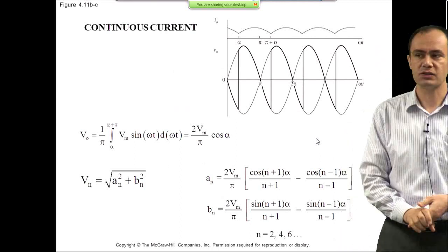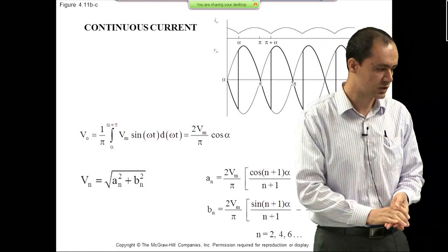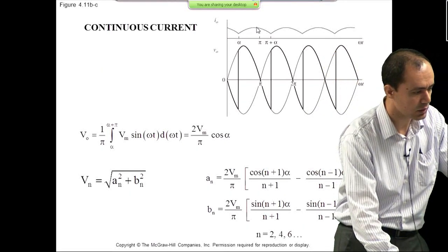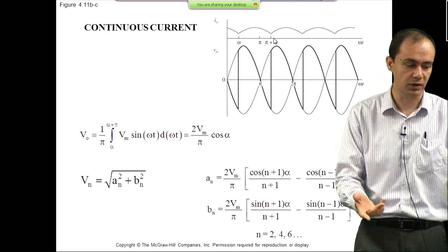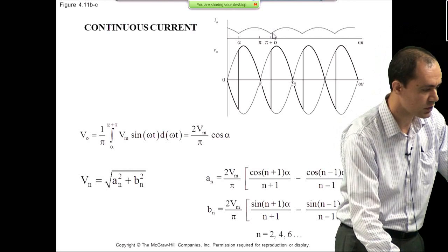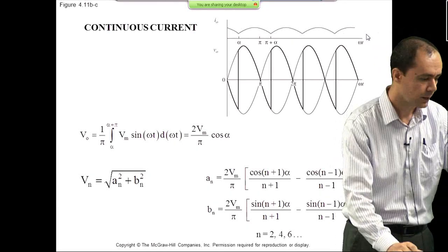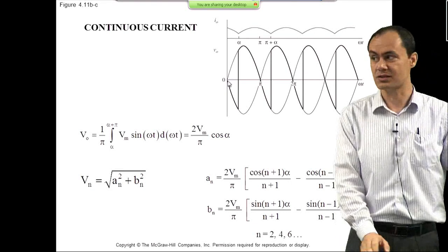And there might be a case that either your inductor is relatively large or alpha, the firing angle, is relatively small. As you can see, the inductor current does not have a chance to return back to 0 before the next firing arrives. So basically, you are going to observe a continuous output current waveform, and your output voltage waveform is not sitting on 0 anymore.